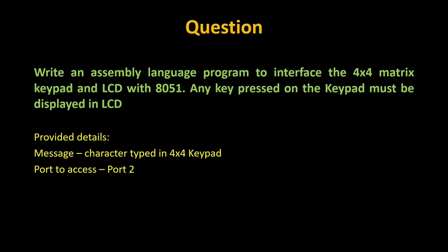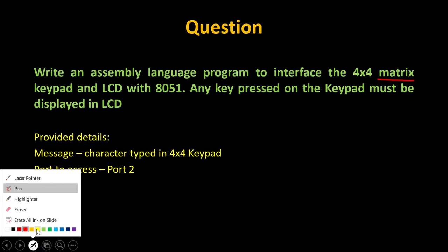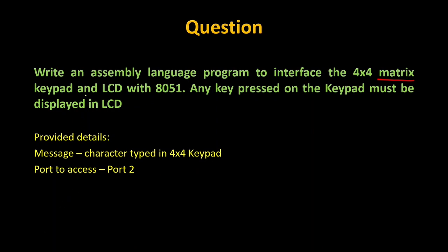The question in front of you is: write an assembly language program to interface a 4x4 matrix keypad and an LCD with your 8051. Understand the word, it is a matrix, right? The LCD is also connected to your 8051.